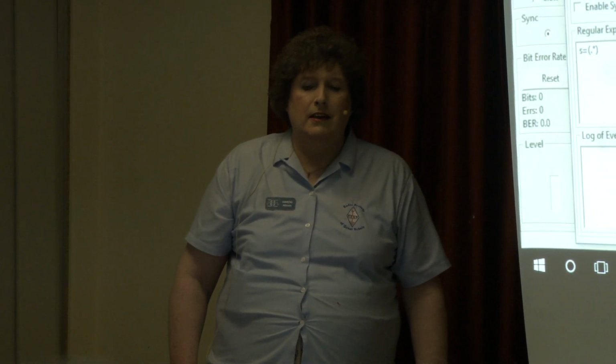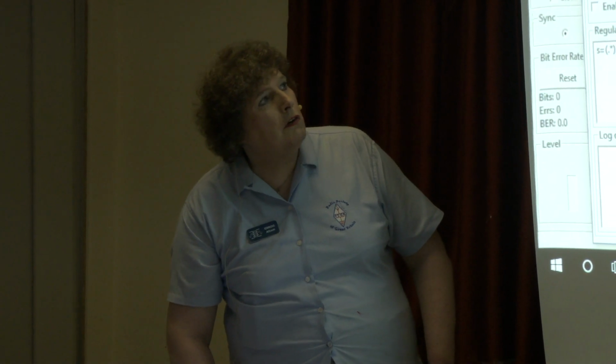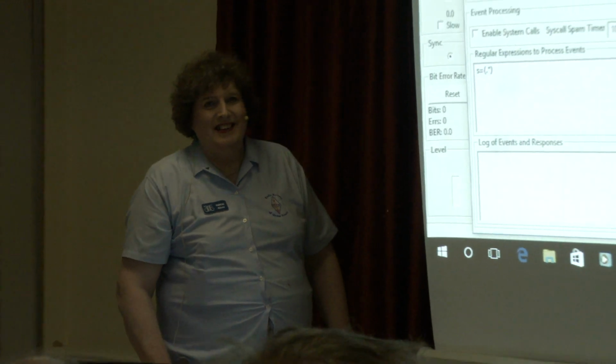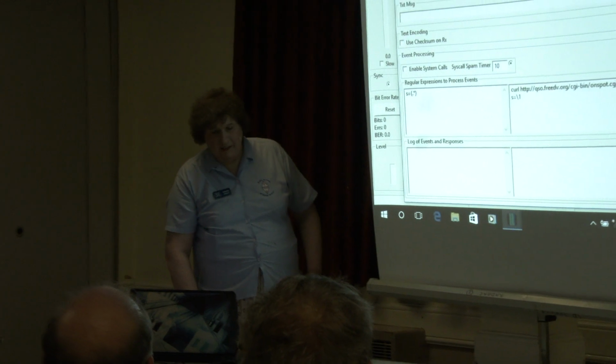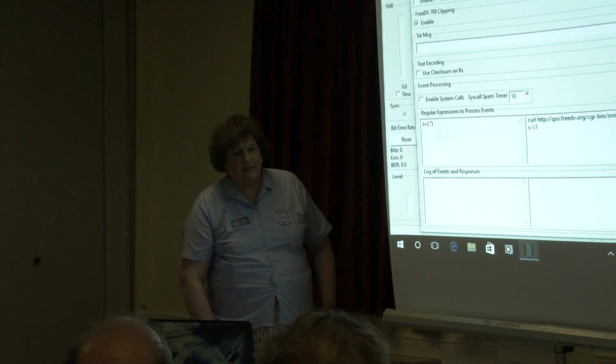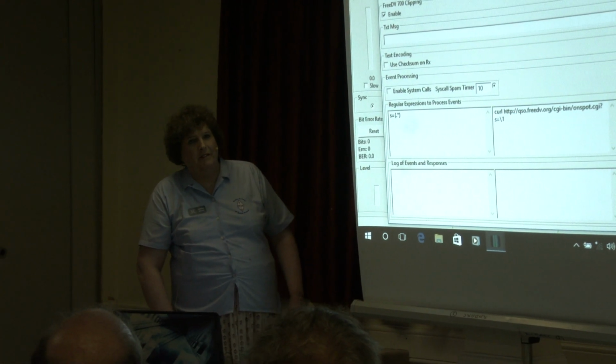Alison, on the wide bandwidth, what's the phase distortion like? Could you send pictures over it? Could you send video? No, you can't send video, it's not wide, but you could send slow scan. Well, I was thinking of 39 TV, you see. Yeah, on this bandwidth you get away with about 6 kilohertz. But there's got to be no phase distortion. Put a square wave in at say 1 kilohertz, you can't tolerate too much ringing.